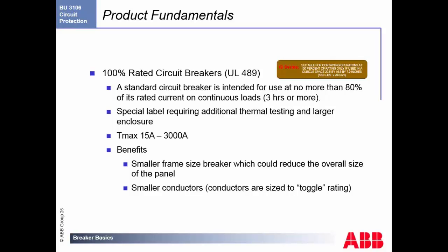These circuit breakers can handle that. It is intended for no more than 80% of its rated current. Again, that's the guideline I spoke to beforehand. Generally, you want to stay within 80% of the rated current. You don't want to push things to 100%. It'll work, but it's not the safest way to use the product. Special label is required for thermal testing.